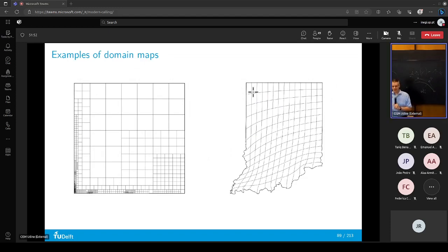Good question. Can we have holes? Yes and no. We can have holes by trimming. Trimming, I think, was in one of the talks, but I'm not sure. Trimming basically means you first do this and then artificially trim away the thing you don't want to have. But that requires a lot of hand work in your solver, because just because you don't see it doesn't mean the solver doesn't. You really have to trim it away in the solver also.